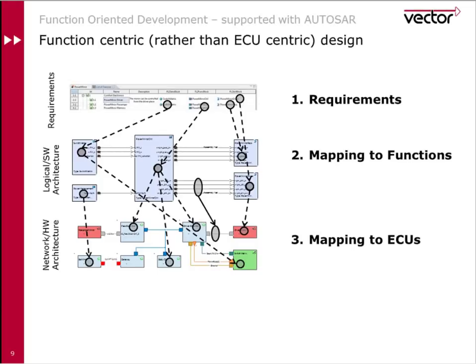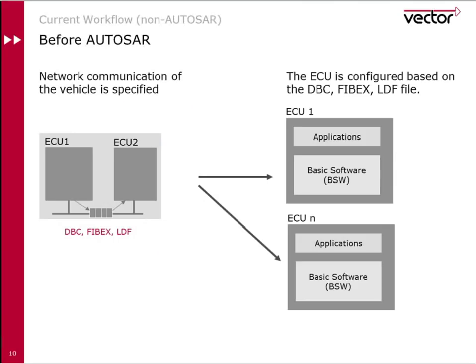And in such a manner, if we have tyre pressure monitoring, for example, designed in an AUTOSAR way, that means, theoretically, the TPMS software can be hosted on, for example, an ABS braking unit, where the ABS braking unit is capable of hosting AUTOSAR software components, but also has some spare capacity and the necessary inputs and outputs. And using this methodology, we can think about designing our vehicle using AUTOSAR in a more function-orientated way rather than a more ECU-orientated way.